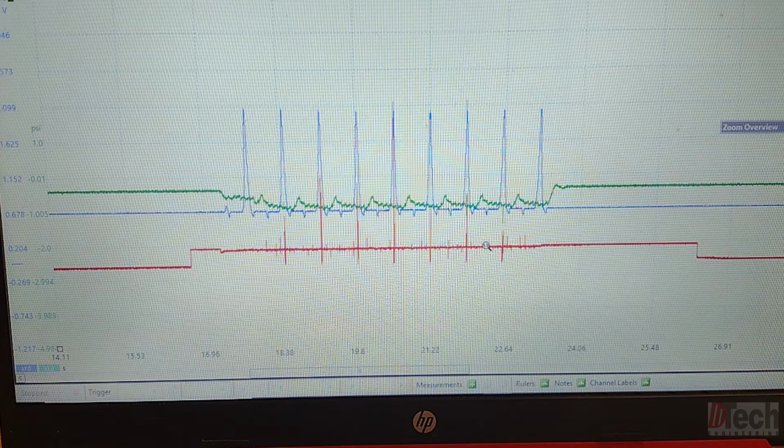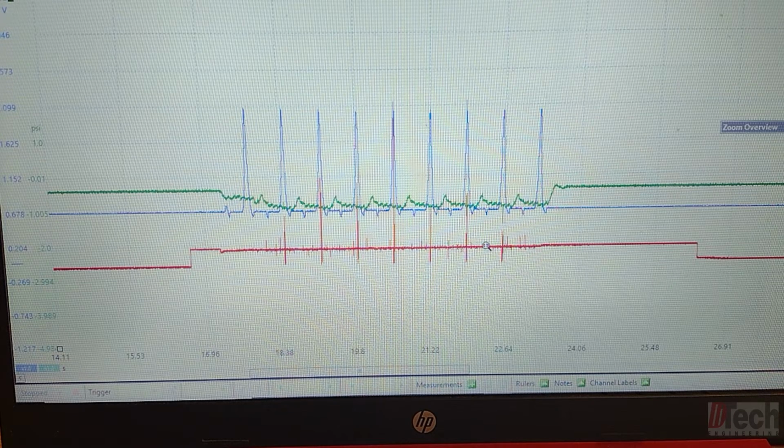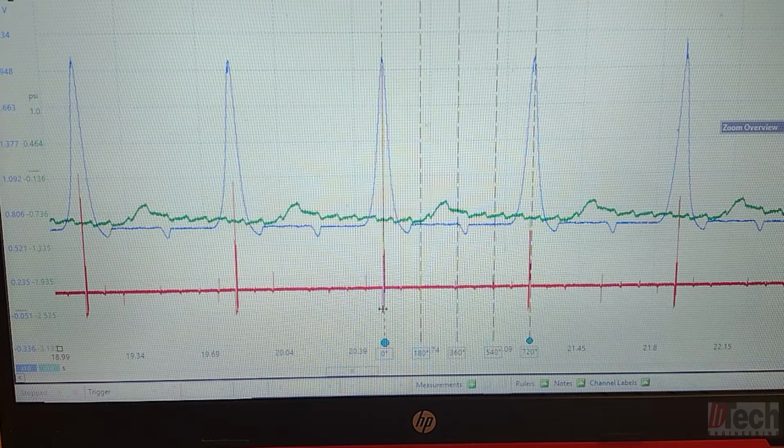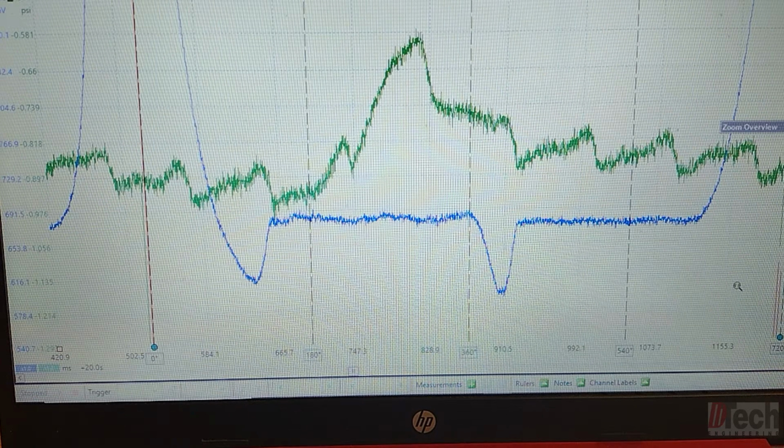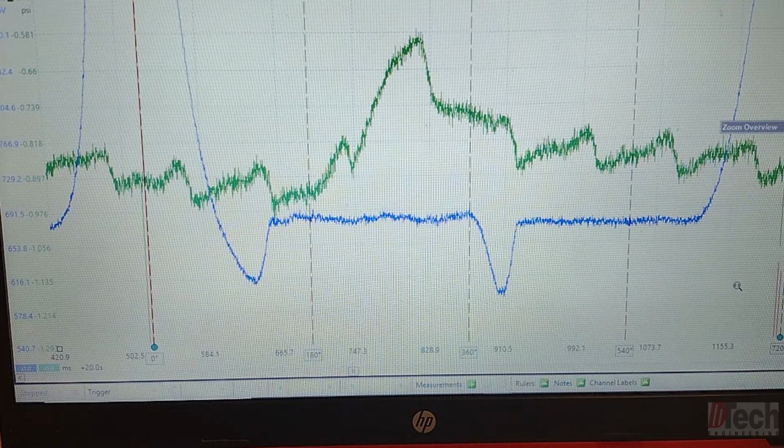As far as this actual capture, this is cranking in cylinder number 1 with the intake trace. Now we know, and ignition for cylinder 1. Obviously we know cylinder 1 is a known good. It's not the one that's misfiring. So if we break this down into the 4 parts and concentrate down here on the bottom, you can see the in-cylinder cranking 4 strokes going on.